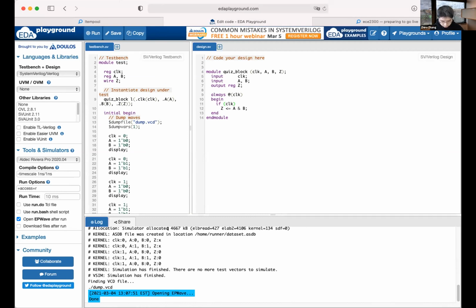Okay, why is it not a latch without the if statement? Because you can switch at clock 0 or clock 1, so whenever the clock changes value, indeed we are sensitive to the change of the clock. But think about the definition of a latch. If clock is 0, then we are not supposed to take new values. Only if the enable is high are you supposed to take the value. That's the definition of the latch. It's level sensitive. Make sense?